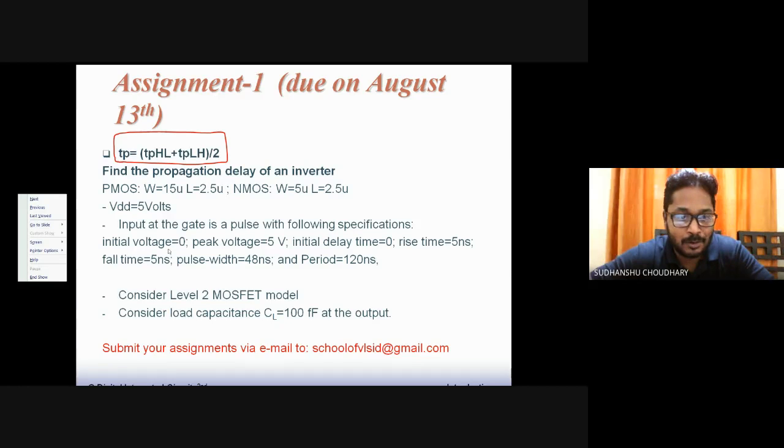Initial voltage is 0. Peak voltage is 5 volts. Initial delay time is 0. Rise time is 5 nanoseconds. Fall time is 5 nanoseconds. Pulse width and pulse period are 48 nanoseconds and 120 nanoseconds. Since you have done an experiment in the lab, this will be a very easy assignment for you.